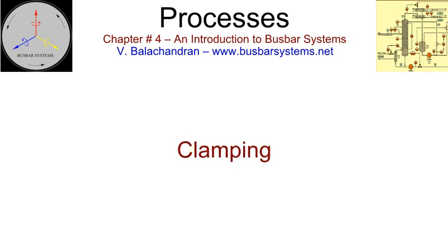Clamping. Clamping of conductors is extensively used in transmission lines and outdoor switchyards. In the switchyards, all the conductor joints and terminations are made with clamps and connectors. Clamps and connectors manufacturing is a very specialized and mature industry. The clamps and connectors installed in a switchyard are voltage specific, as they are tested for corona discharge. Clamping has the advantage that the ends of the bus bars do not need processing for jointing. This allows a certain amount of flexibility that is needed in switchyards where tolerances are large.